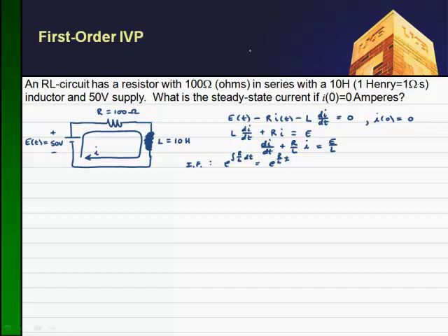So we multiply that through, distributing across the left hand side and multiplying on the right hand side. Let's go over here, and I'll just write the exact differential, so I am skipping steps: the function I of t times the integrating factor, e to the R over L times t, is equal to the right hand side times that integrating factor, e to the R over L t.